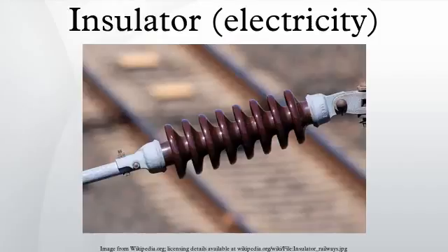Telegraph and power transmission insulators. Overhead conductors for high-voltage electric power transmission are bare, and are insulated by the surrounding air. Conductors for lower voltages in distribution may have some insulation but are often bare as well. Insulating supports called insulators are required at the points where they are supported by utility poles or transmission towers. Insulators are also required where the wire enters buildings or electrical devices, such as transformers or circuit breakers, to insulate the wire from the case. These hollow insulators with a conductor inside them are called bushings.